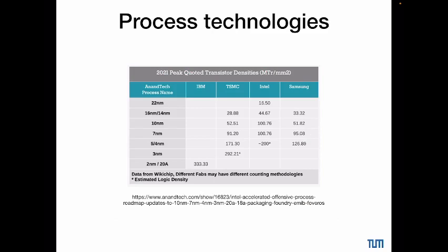This indicates a little bit how many million transistors you can actually integrate on a square millimeter of silicon. And here are the processes. So we have the 10 nanometer here, so it's about 100 million transistors per square millimeter. And you see that for 7 nanometer, the density did not increase in the Intel process, but when switching to the 4 nanometers, they will double the density.